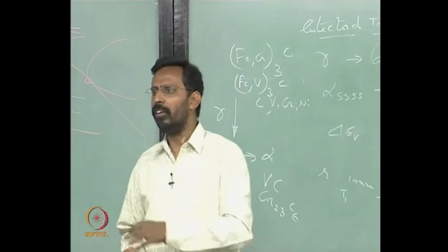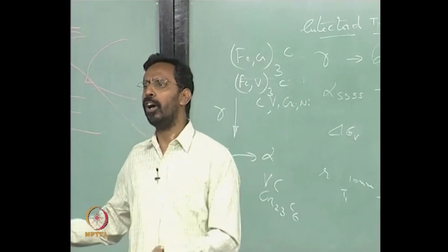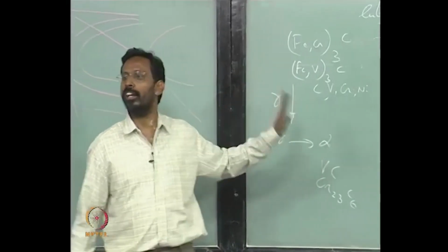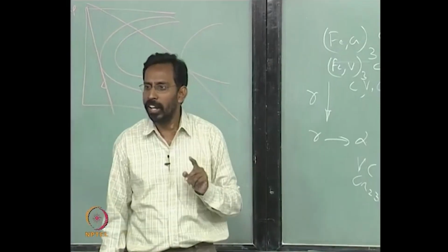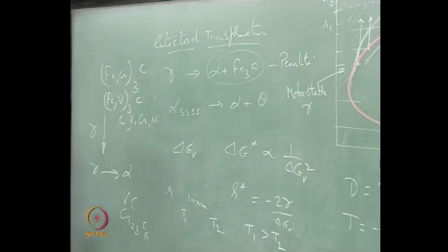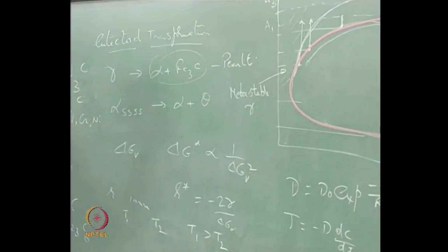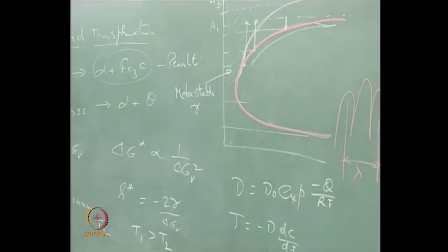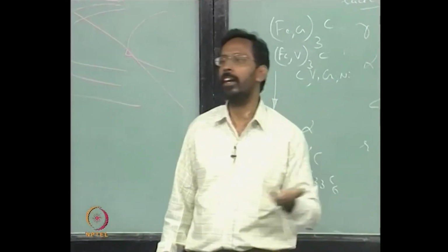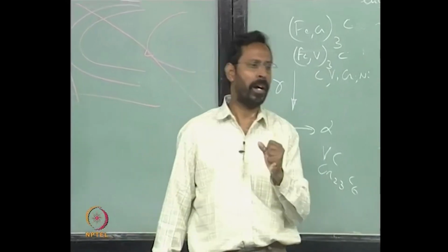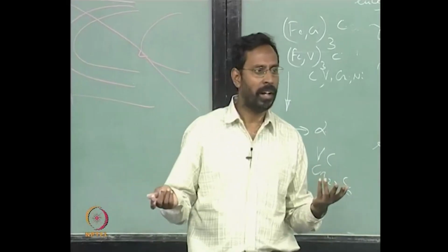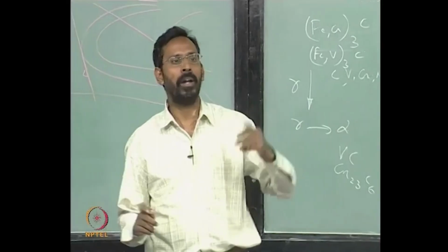So it is a question of whether it can dissolve or not. If it does not dissolve, we do not talk of dissolution at all. Whenever I say it dissolves, all these elements that we are talking about can dissolve, including tungsten. The only reason is tungsten can dissolve at a higher temperature. That is why, whenever we talk about high speed steels, the austenitization temperature is almost 1100 to 1200 degrees, because for tungsten carbide to dissolve into gamma, you need very high temperature. The stronger the carbide, the higher the temperature you need for it to dissolve. It has to first break and then only dissolve, both carbon and tungsten.